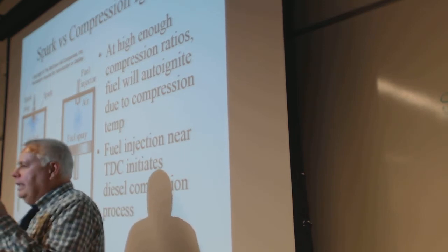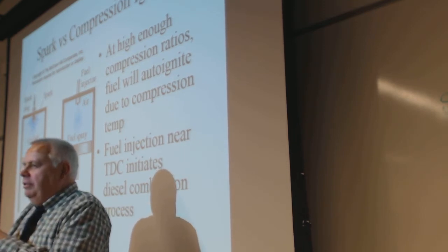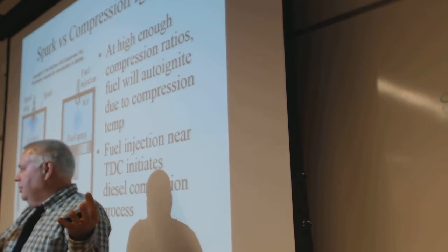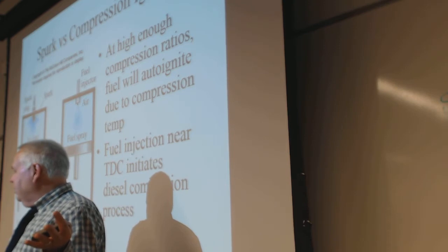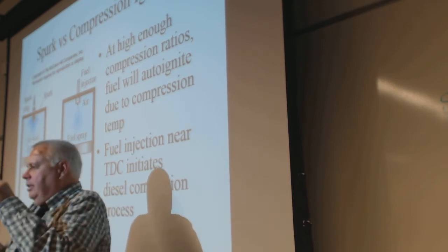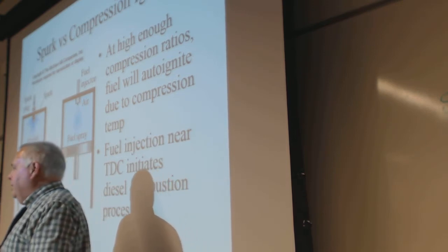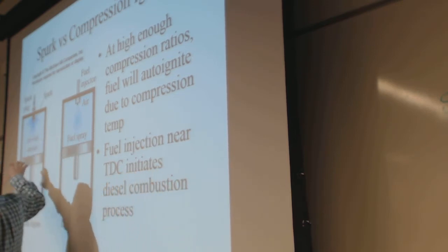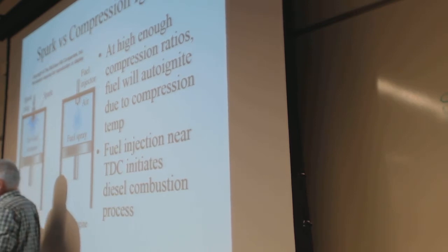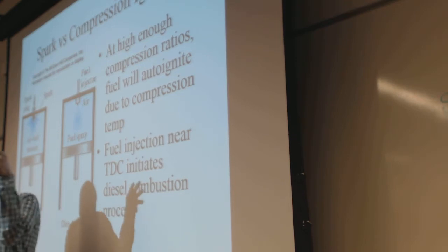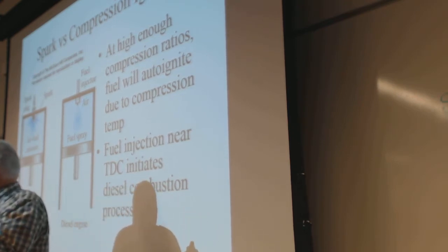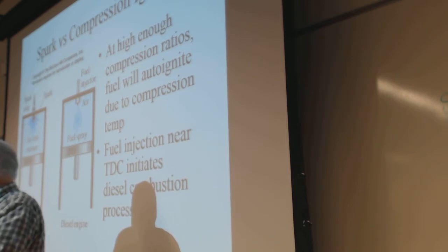On diesel, the only way you're going to get it to come up to temperature enough is if you have a full charge of air in there all the time. So the diesel has no throttle. It doesn't pull against a vacuum at low power loads. It's just free breathing, and then they close it, and then it comes all the way up. Instead of controlling the mass of the air-fuel mixture by reducing the pressure with restrictions, if you block it here and cause this volume to happen, it's going to stretch out the charge and it's going to become less dense, less pressure.